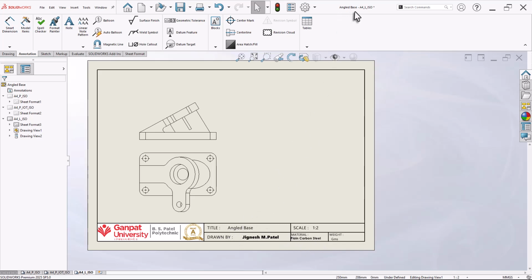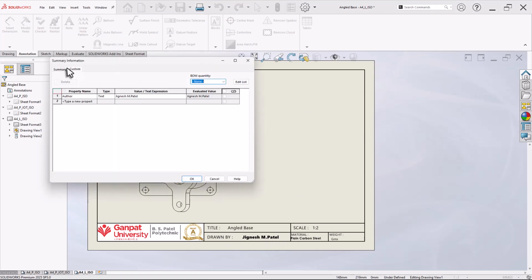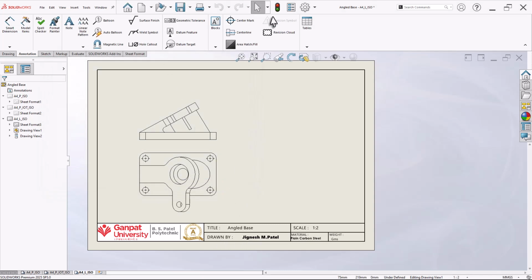Because I have added the part, whose name is directly taken to the drawing file, its name also appeared. Now how did my name appear? Let's go over here. Under this property, under the custom tab, I have already added the author, which is a custom property, and my name. This is linked to that property, and that is done through the template creation process.